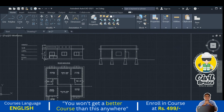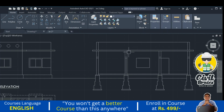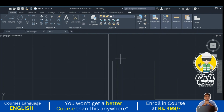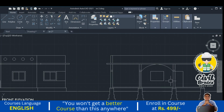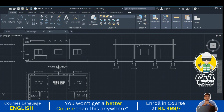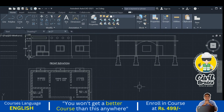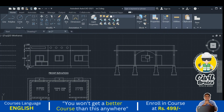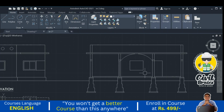Clear? If it is an arch, for example, then we need to show a small arch over here. The arch will start from lintel level, from here, like this. If it is an arch, then we need to show the arch. It is not mentioned whether it is an arch or a direct opening. Whether it is movable things like this also we can show. Not mentioned, so I just delete this one.